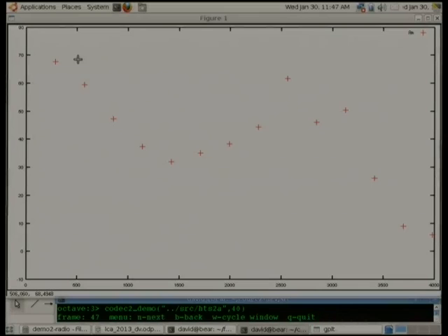Now, that information evolves over time as the person articulates the words. So as we move forward in time, you can see it slowly varying. So we're just stepping forward in time. Every 40 milliseconds you see it slowly evolving. So because it's evolving, we have to update those amplitude samples at the decoder, so we tend to retransmit a bunch of samples at regular intervals, say every 40 milliseconds. And that's pretty much how Codec 2 works.